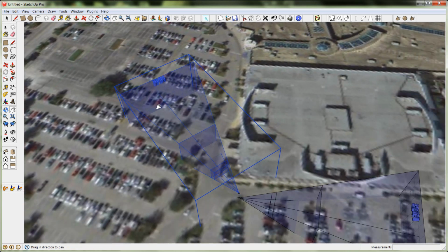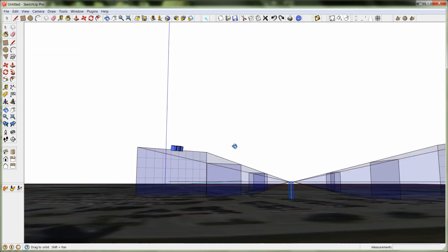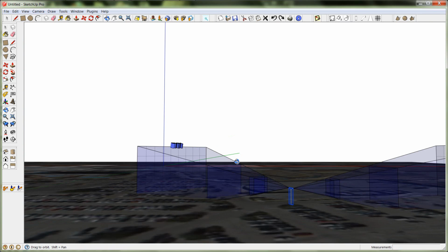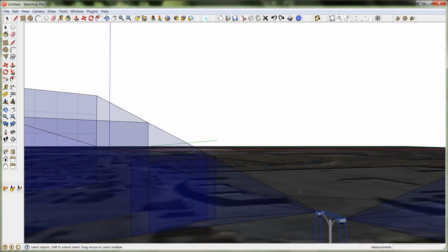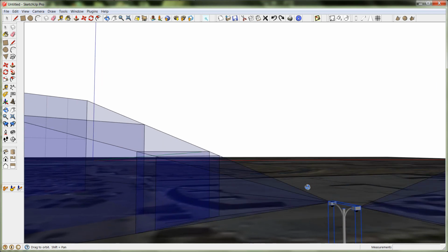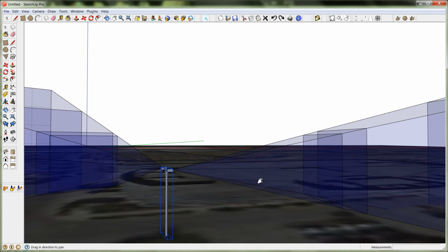And then I can go ahead and position my lens however I decide is the proper way. So they want it looking out here into this area of the parking lot. Well, it's PTZ, and have it looking wherever I want. Or maybe I want it as a default looking down the side of the building there. But in any event, what we have when we're all done is a 3D representation of the two fields of view of the lenses and the camera pole, the PTZ pole itself.